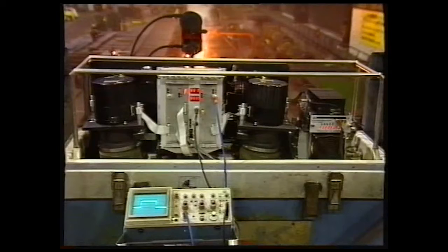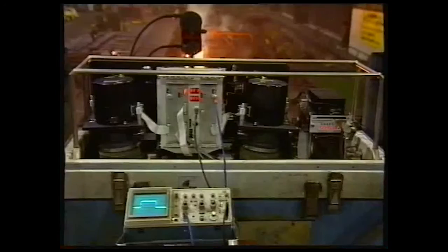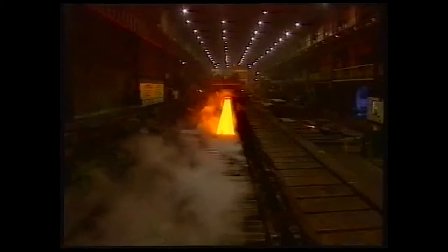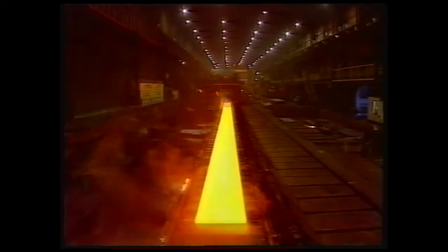The glowing steel yields a high contrast image. The grey level signal from one of the linear CCD cameras is shown on the oscilloscope screen. The plate edges clearly stand out. They are found as steep dark-bright and bright-dark transitions. However, width as seen from an overhead camera no longer matches the true plate width if the plate is warped or bended. This explains the need for a second camera.